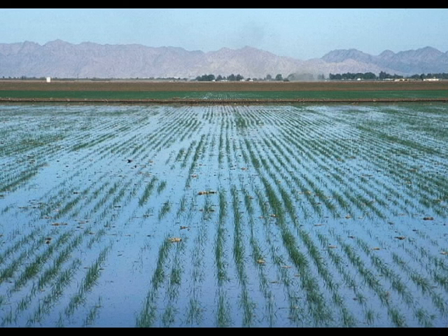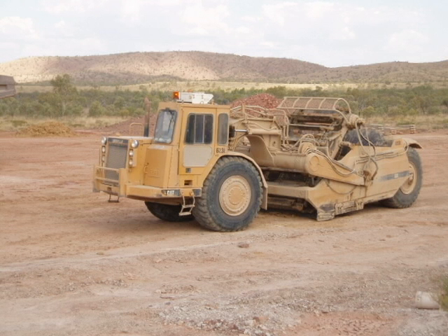The ideal land surface for surface irrigation has little or no cross slope and has a uniform downfield slope that is slight enough that erosion from rainfall and irrigation water is not a problem, and adequate enough to provide good surface drainage. If the conditions are appropriate, the ideal land surface is flat in both directions. The slope limitations vary from location to location because of differences in soil and rainfall.